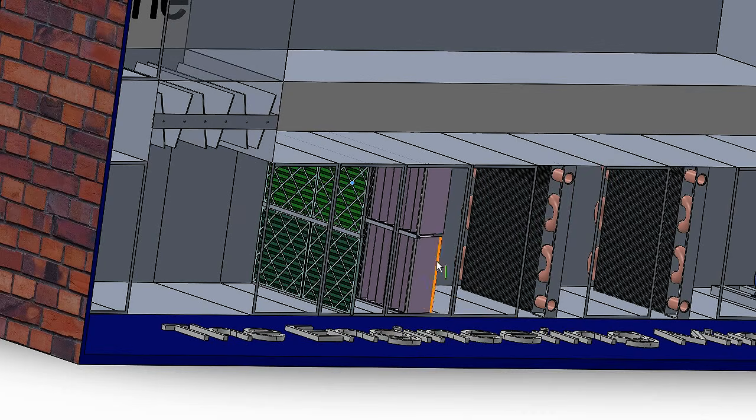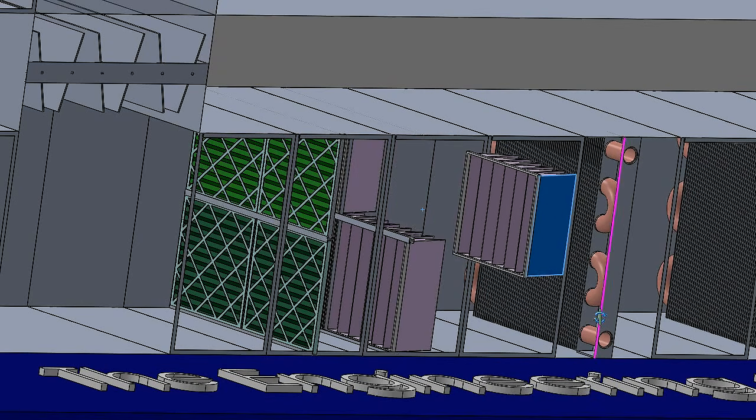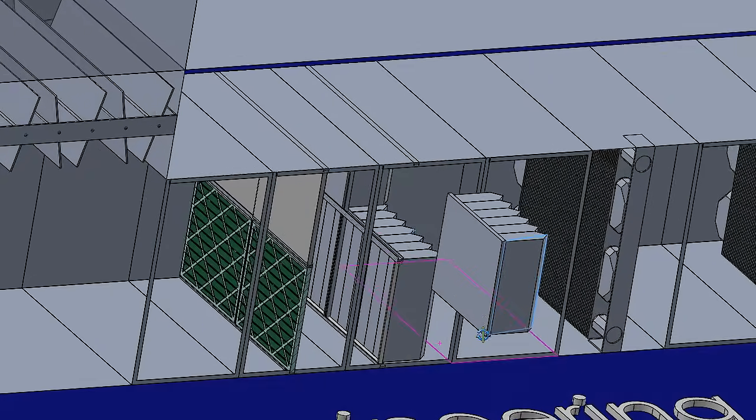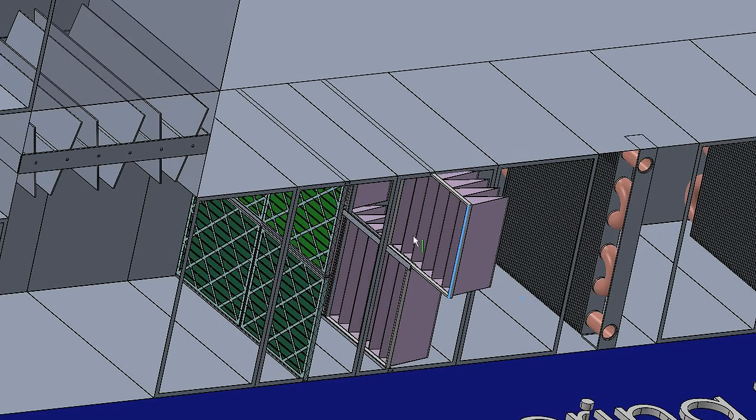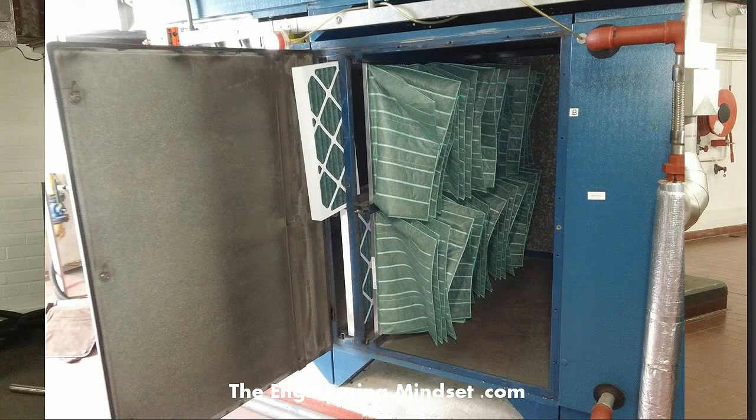The second line of defense there is your bag filters even, and these usually have these jagged edges, so the bags go back a certain distance, and they will change that. And that changes, if you imagine, the surface area that it can capture. So it comes along there, and these can slide in and out. And the real bag filter installation will look something like this.